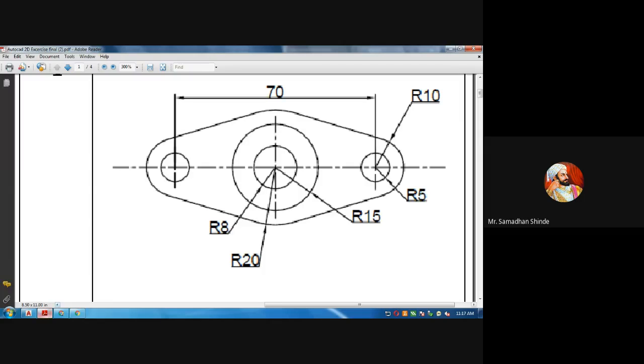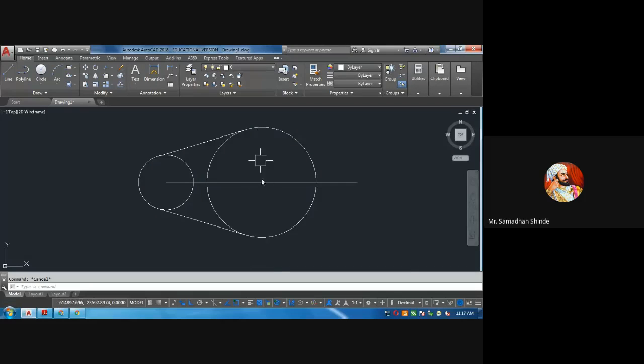So you can take mirror here about both the axes. So you can select now mirror image. MI, enter, shortcut of mirror. MI, select object. You have to select the circle and these two lines. Only this much you have to select. What I have selected: one circle and two lines.